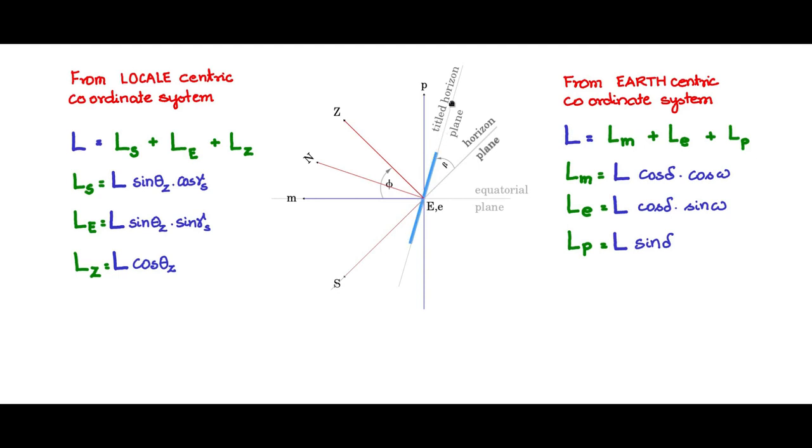Now this is the tilted flat plate collector, tilted at an angle beta with respect to the horizon plane, and this is the tilted horizon plane. And what is of interest is the insolation along this axis, the normal axis or the n axis, normal to the flat plate collector, which is tilted. So let us draw that, and I will name that one as Ln vector.